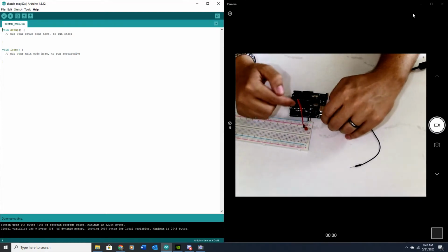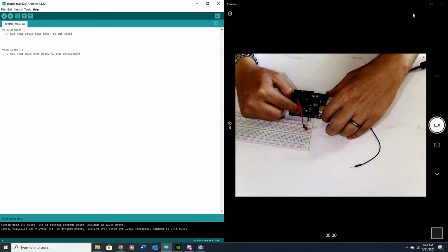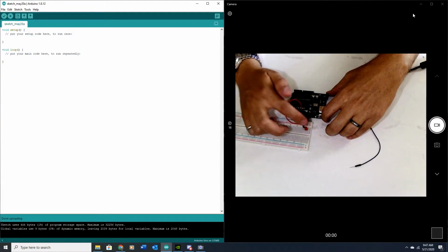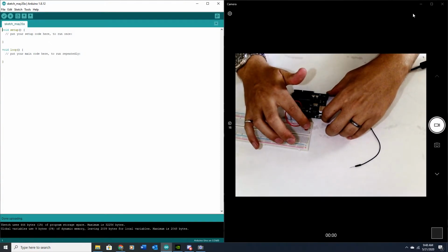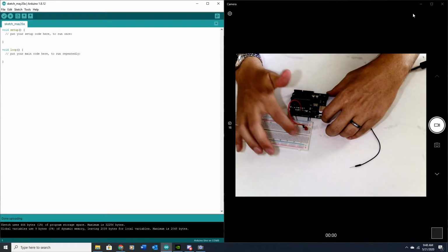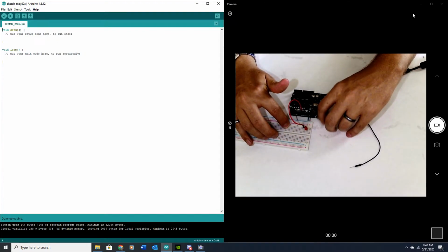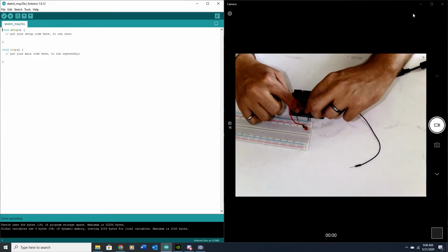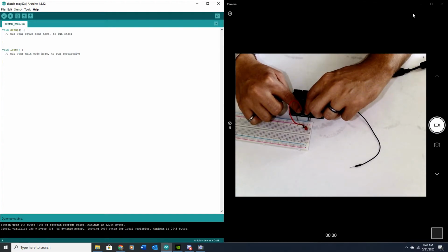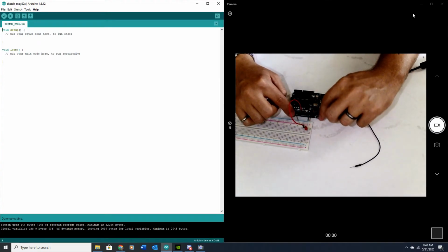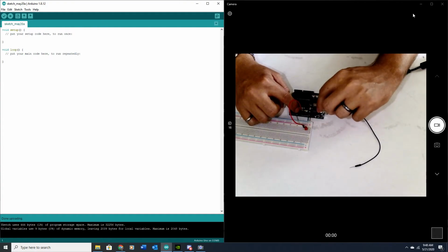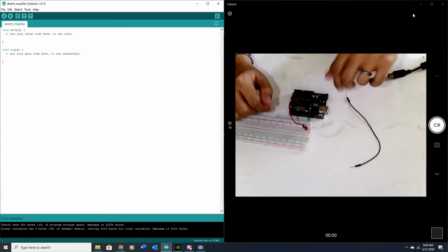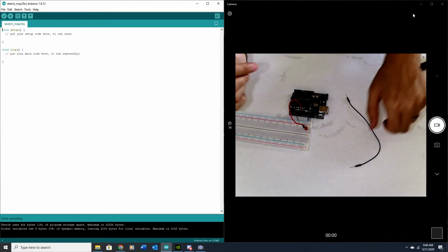Right. So again, I'm going from my pin 9 socket to my breadboard. The breadboard connects the jumper to the anode on the LED. Then the cathode on the LED is connected to the resistor, again through, this is row 2 on my breadboard, and then that goes back to ground. So this is going to complete the circuit, and hopefully if I set this to 5 volts, which is a high, it'll turn the LED on. And then if I set it to a low, which is 0 volts, then there'll be no difference across it because the ground is at 0 volts, and it will be off. So I control whether or not this is on or off using my code.